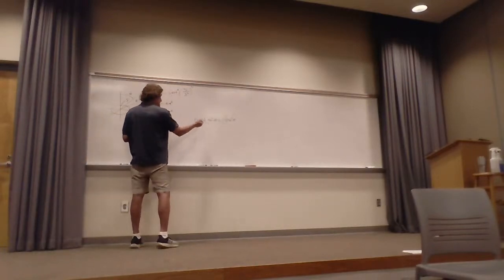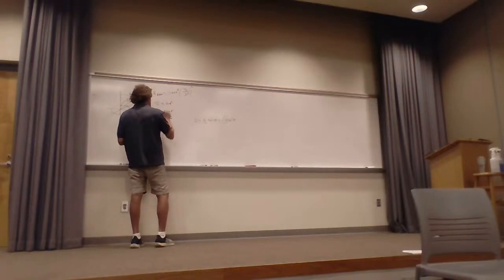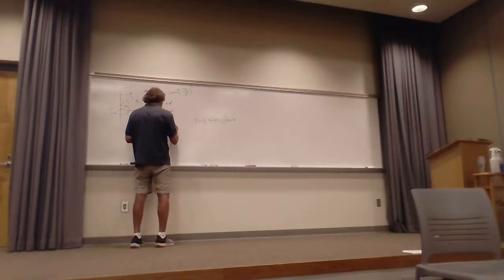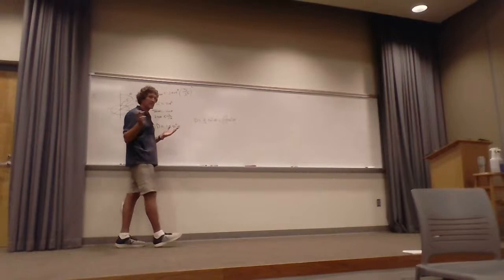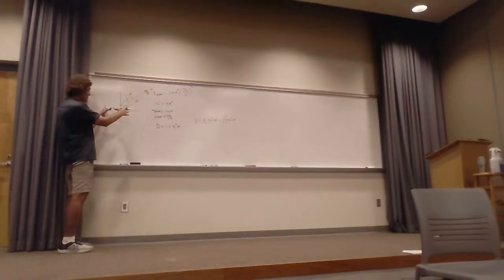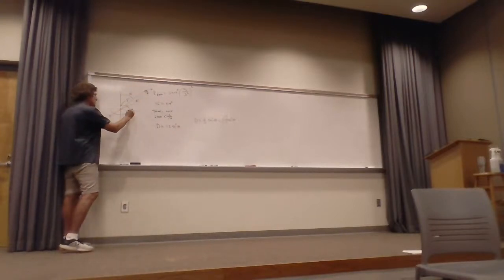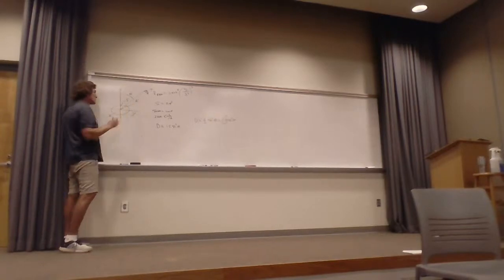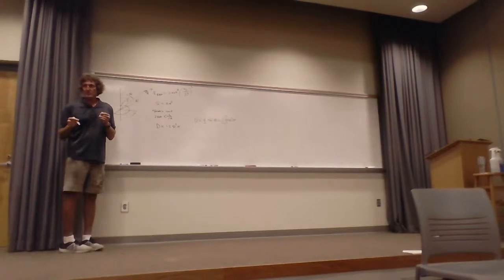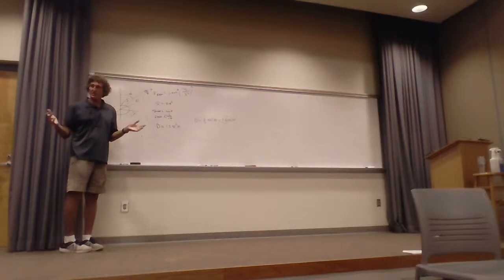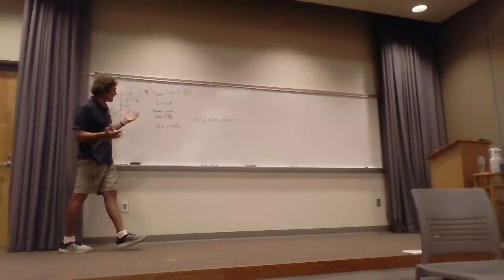And the directivity will be the same. So the directivity for this small loop is 1.5 times the sine squared of theta. This assumes it's oriented in the X, Y plane, perpendicular to the Z-axis. In other words, it's concentric with the Z-axis.